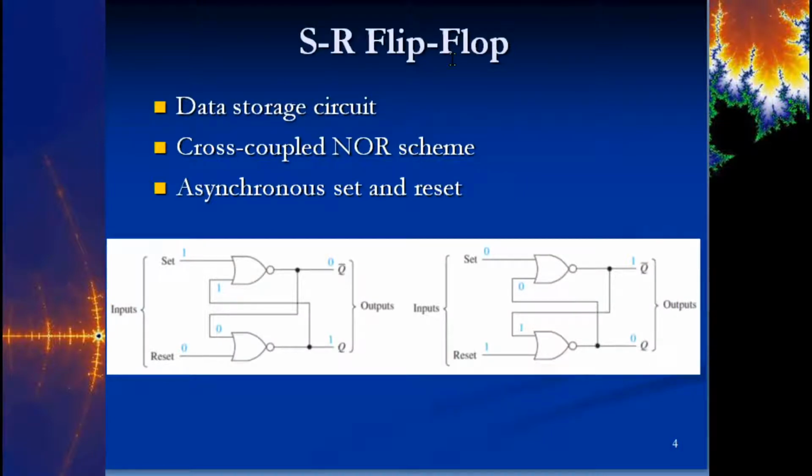Okay. So the very base of what we're going to talk about today is called the SR flip-flop, and that stands for set and reset. So we call it the SR flip-flop. It's a simple data storage circuit, okay, and it's not like it has a memory location where it's going to store it like a hard drive, okay? If you notice in the picture here, the way that we're storing it is we've got this cross-coupling back into the previous gates. So there's constant updating going on, right, if you can see that. So that's how we can retain the state, because we've got a constant feedback here.